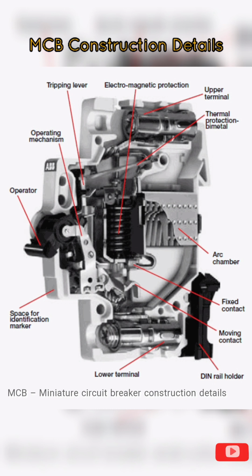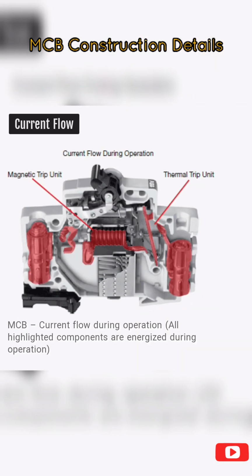Thermal, magnetic trip units. Current limiting breakers use an electromechanical, thermal, magnetic trip unit to open the breaker contacts during an overcurrent event. The thermal trip unit is temperature sensitive and the magnetic trip unit is current sensitive. Both units act independently and mechanically with the breaker's trip mechanism to open the breaker's contacts.